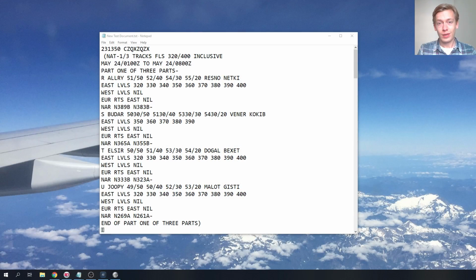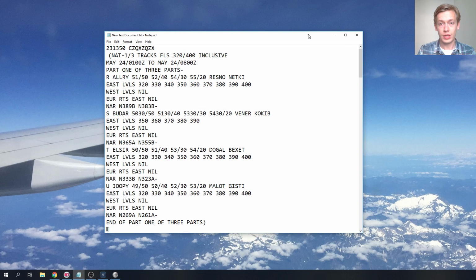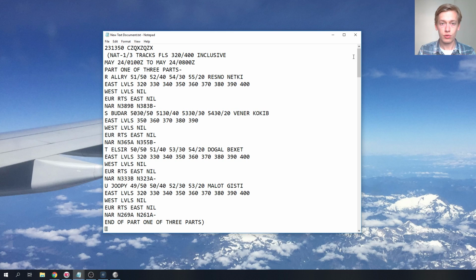Okay guys, so we're now going to take a look at the flight planning part of this tutorial video, and first of all I have here today's NAT Track Message, so we can go through it and decode it. It's pretty straightforward. It seems like a lot of text, but you just have to take this step by step as usual. So we have the NAT tracks between flight level 320 and 400, valid on May 24th from 1 Zulu till May 24th at 8 Zulu. Now, these NAT tracks are only valid for another 13 minutes, but that's okay. As you can see, these are the tracks that go from the US to Europe. So these are eastbound tracks.